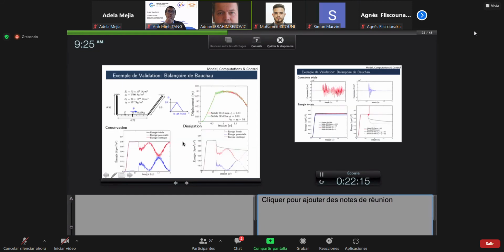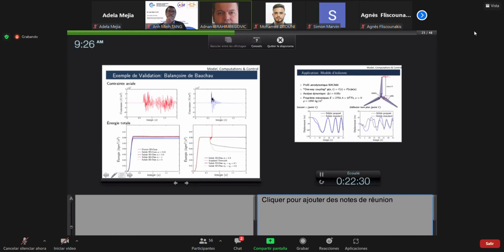And you can see that in this computation. This is again Bosch's string, but computed from 3D solid elements. And you can see that basically we have the same desirable effects, that decaying of the energy starts here with this scheme, and that basically the axial force is not computed well with the conservation scheme, whereas here it just comes down and you keep it constant over the time for the energy decay scheme.